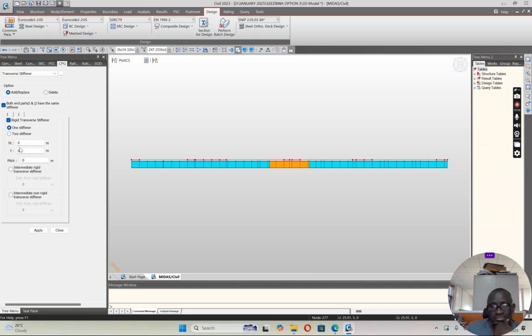And so it is very important that we know the spacings, and the sizes matter a lot. For this case, I think we need to write up something on the stiffeners, where the detailing is to be appreciated. The height of the stiffener you need is from the bottom of the top flange to the top of the bottom flange, where we expect to have the stiffener.